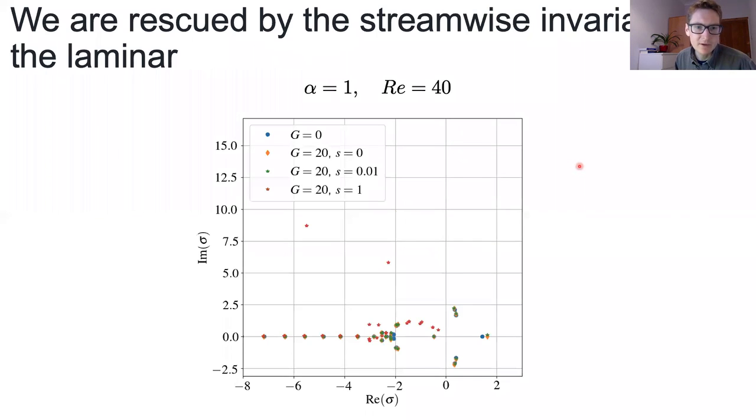And you continue increasing the shift, and then the whole spectrum can be swung around into the left-hand side, and you've managed to stabilize the solution at relatively modest amounts of gain compared to the 2000 that I showed you that you needed to go to stabilize without the shift, even those complex eigenvalues.